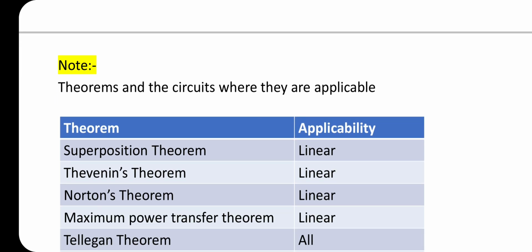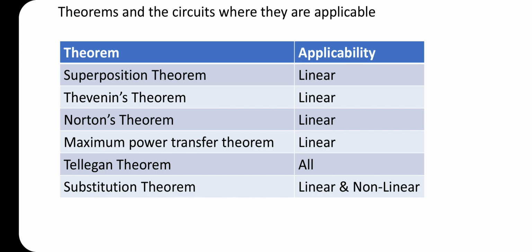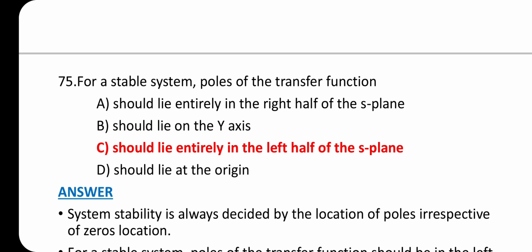Note, theorems and the circuit where they are applicable. Theorem and applicability. Superposition theorem, Thevenin theorem, Norton theorem, maximum power transfer theorem, all are applicable in linear circuit only. And Tellegen's theorem can apply in all circuits. Substitution theorem also can be applicable in linear and non-linear circuits.